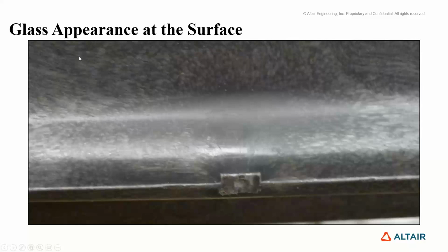First it's splay, and farther out you see glass emerging in it as well. And along here you see the glass in it. You can see the fibers right near the gate as it forms. So you have kind of a mixture of splay and glass as it goes out. And that can affect the mechanical performance of a part.